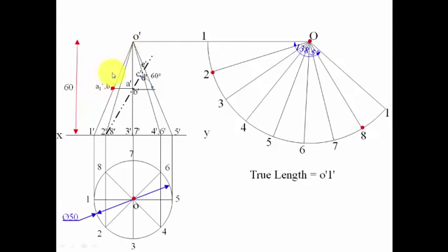Alright, so now what you need to do is keep one leg of your compass here, other leg over here, then with O as center you need to put an arc, something like this, and this is going to be your point A. Alright, and again with that same radius we need to put an arc over here along this O7. Okay, so you're going to have point B.